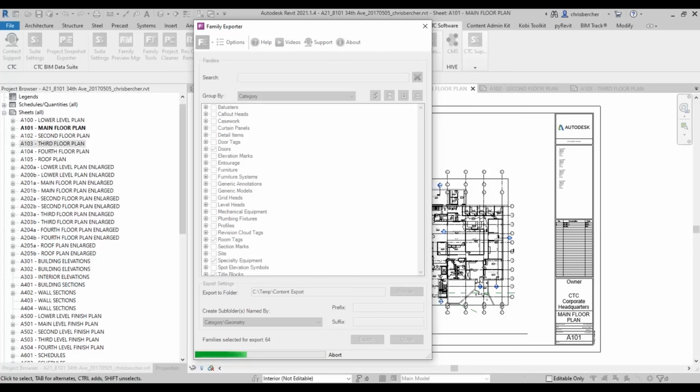And if you need to audit it, great, there we go, easy fix. Maybe it's got a bunch of warnings in it for whatever reason. It's an exploded AutoCAD object inside of a Revit family, right? We can get that cleaned up, reloaded into the project, and save ourselves from a bunch of extra warnings that we didn't know we had initially, or that we couldn't resolve with just a standard Revit audit. So this tool does have a number of different uses, not just exporting content from a project.